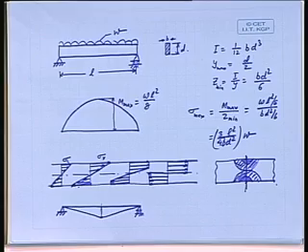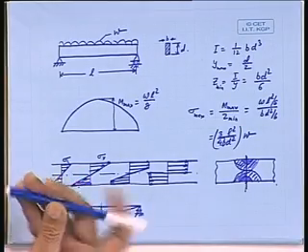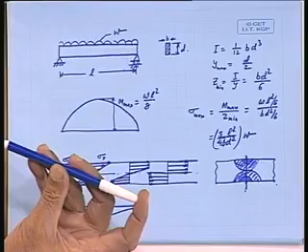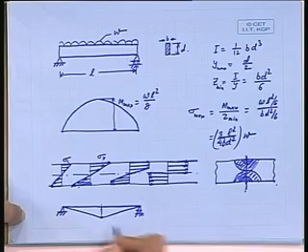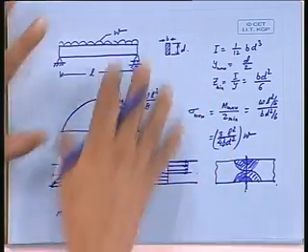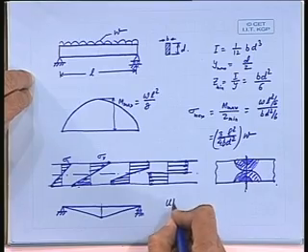So that's what happens. Actually if you try to have 2 hinges here, support it and load it, it will simply go down like that. So if it goes down like that, then we say that this structure has now ultimately failed. Okay. So we term it also ultimate failure.